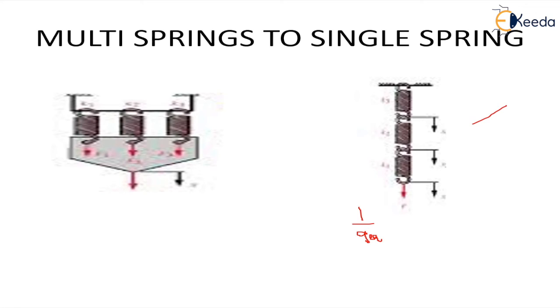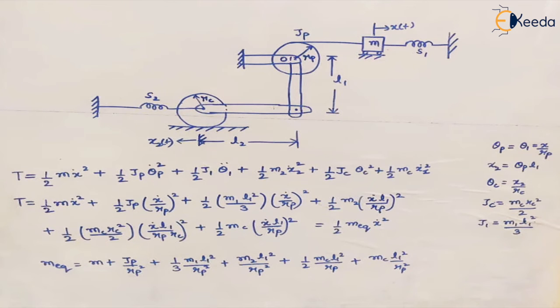And in case of parallel, k equivalent is equal to k1 plus k2 plus k3 and so on. So by using these equations, you can find the spring stiffness, whatever the number of springs in a system. Here we have taken a simple example to find the equivalent mass of the system.